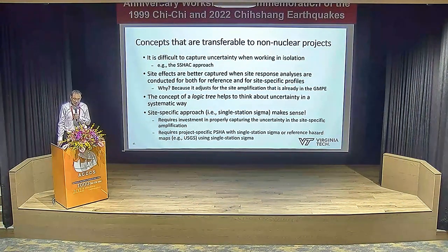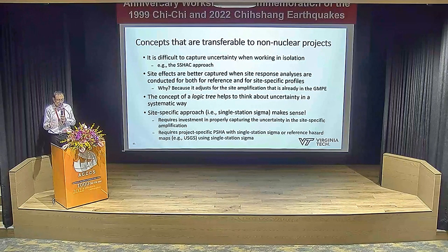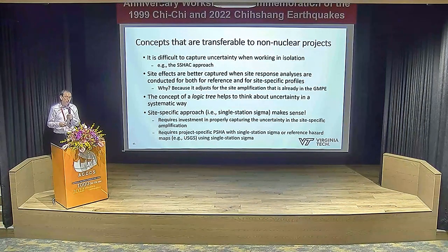It requires investment in properly capturing the uncertainty in site-specific amplification, and requires a project-specific PSHA with a reference hazard that's conducted using single-station sigma. For general projects, that doesn't exist yet, but hopefully this is a direction that, at least in the US, the USGS is going to take to produce hazards using single-station sigma.